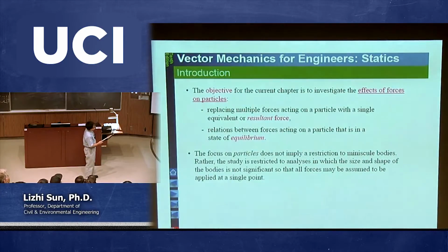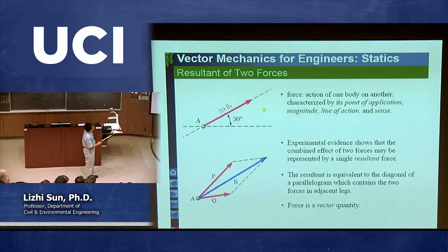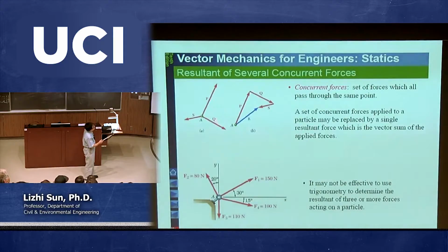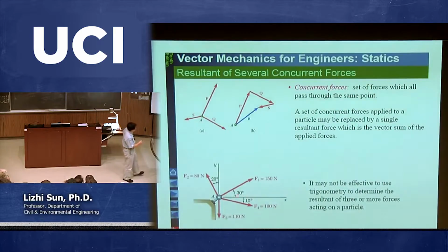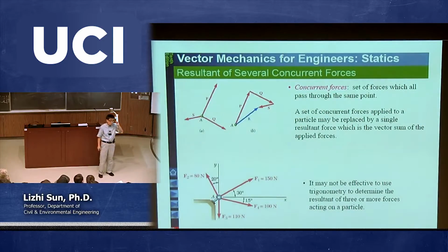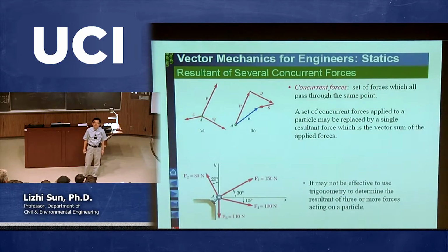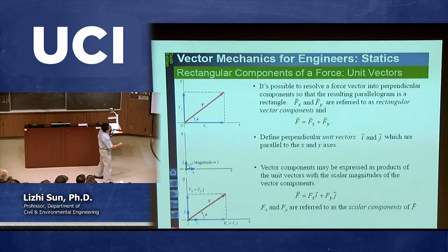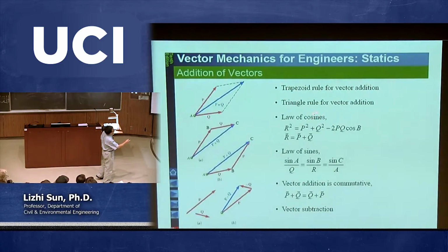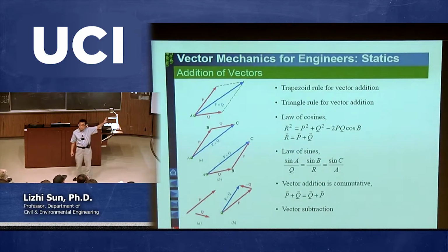No matter what, for two-dimensional problems, we need to know how to decompose any force into x and y components, okay? Especially when you have multiple forces acting on the same point, the best way to solve the problem is to use the component method. And actually, pretty much all examples I talk about, no matter which chapter, I always use the component method, if you recall what I have taught so far, right? I never use what is called the law of sine, law of cosine. I did mention it briefly at that time, but actually I never use it. Which means you don't have to use this method to solve.